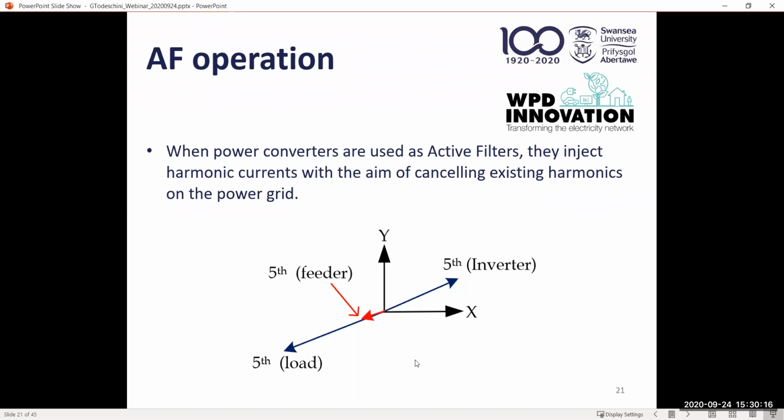In this picture, deliberately, I show that there is some residual current, just because in practice it's very difficult to cancel exactly existing harmonics, mostly because harmonic currents in the system keep changing in time, they're not constant. But as I said earlier, the standards do not generally require complete absence of any disturbance. So if we are left with small fifth harmonic components, that is acceptable.